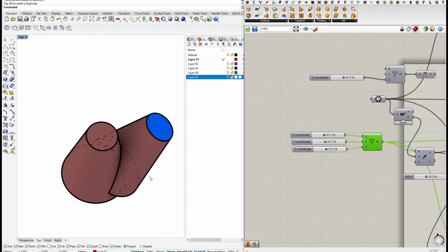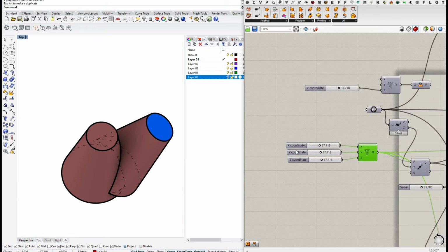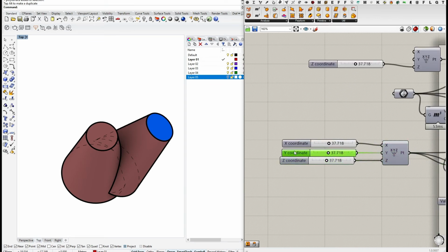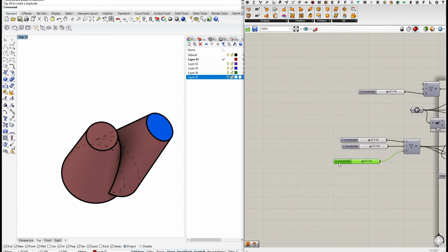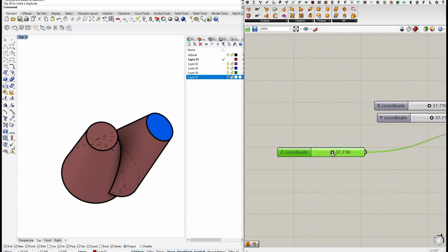Of course, you can animate the object. It can be any form of transformation or anything that runs in your Grasshopper script that you can animate. But we will very simply do an animation where the z-axis of our camera view is being animated.